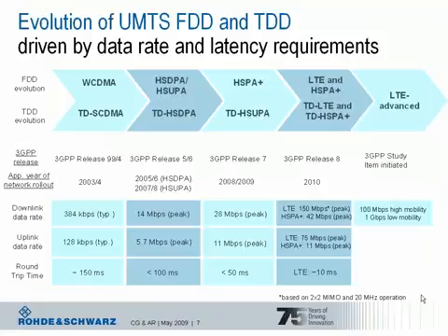But LTE is not the only part of 3GPP Release 8. There are also HSPA Plus improvements that are part of Release 8. This is very important because very interesting features for HSPA Plus are coming up here. You see that the data rate for HSPA Plus could be further improved up to 42 megabit per second by combining 64 QAM higher order modulation and MIMO.